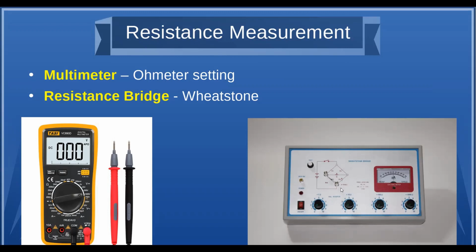And the theory is that when this one equals, these two are equal to each other. When you get this side that you're adjusting equal to this value, the voltage in here will be zero because it's a balanced bridge. So you've got the same voltage drop through both sides. And again, that was named after some guy named Wheatstone.